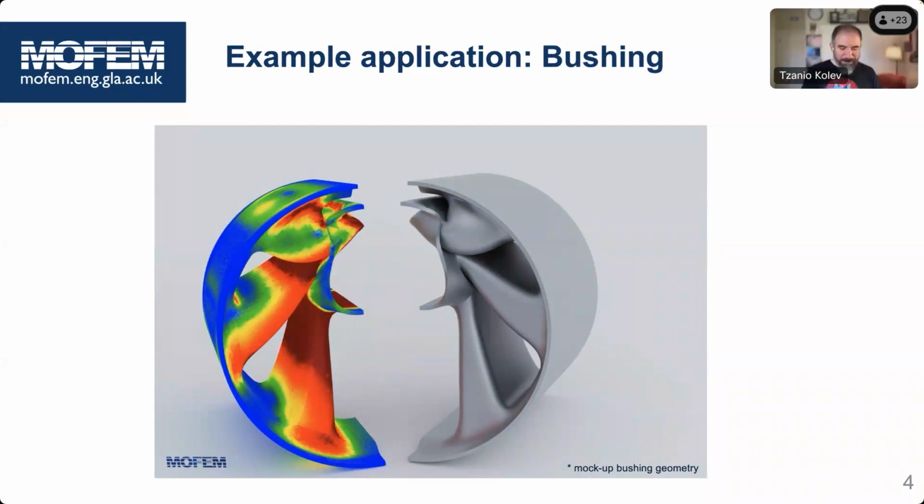It takes a lot of time. That's understood. So you want to have an approximation which runs on tetrahedrons. This is what you need. Okay, but I mean this particular one is certainly not that difficult to mesh with hexes, and you could run on the hex version of this.